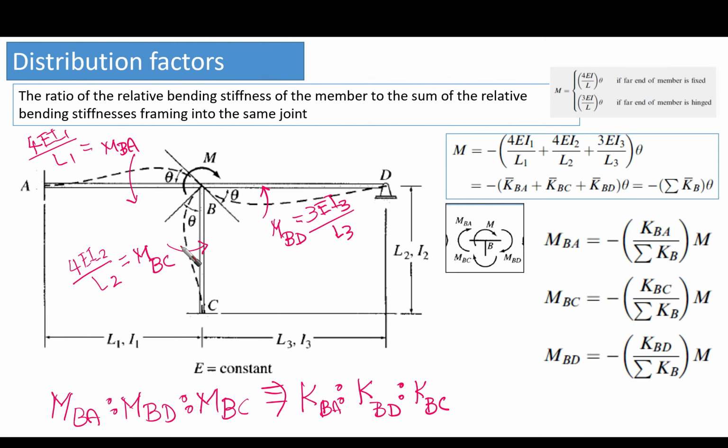So now, let's go back. The beam is going to resist this moment. Every beam is going to develop the magnitude of moment that is related to theta. Take care that theta, because we are talking about the same point and the same moment applied. So theta of member BD is going to be the same as theta for member BC, equal to theta for member BA. So we have the same theta. Why? Because it's the same point and the same moment.